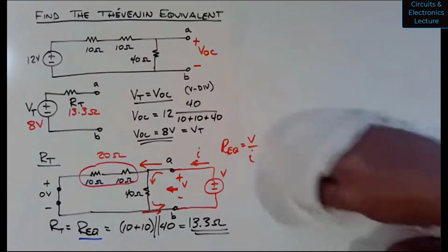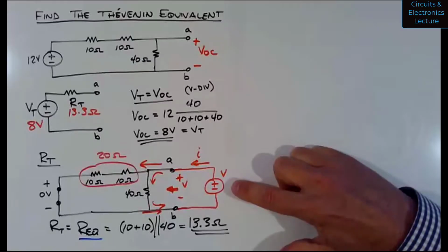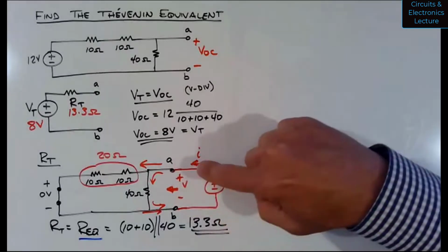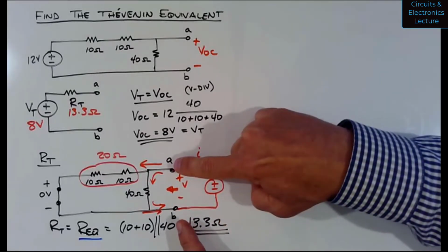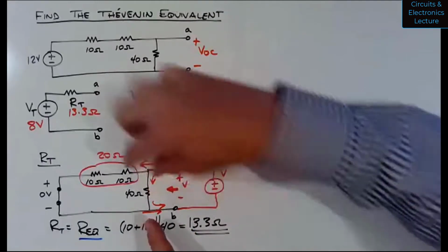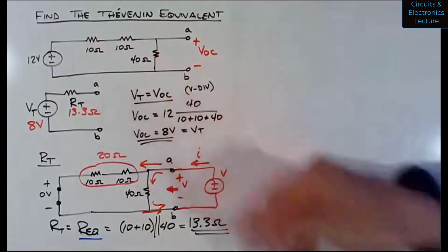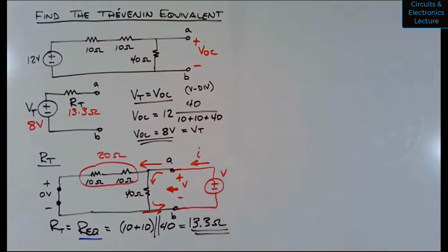No, good questions. Okay. Professor? Go ahead. Sorry, just to quickly clarify. That red node with the red voltage source there, that's all essentially imaginary, right? That's just there for the sake of finding REQ. That's right. If you just recognize that between A and B, the 40 ohm resistor and the combination of the two 10s in series are in parallel, then you wouldn't have to draw any of this. Okay, thank you.